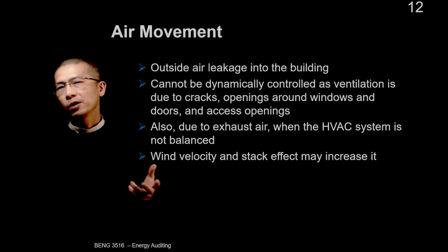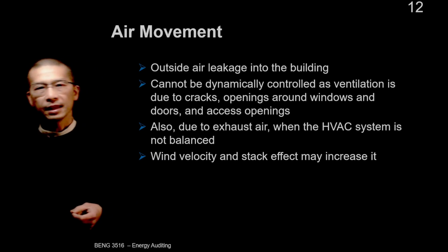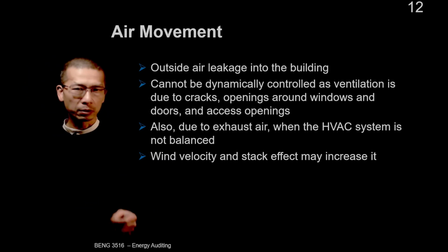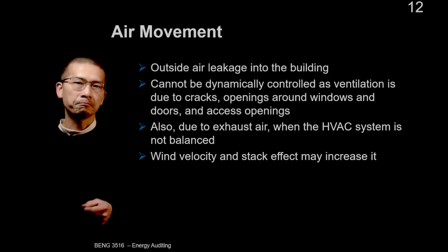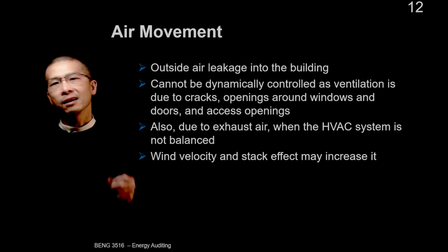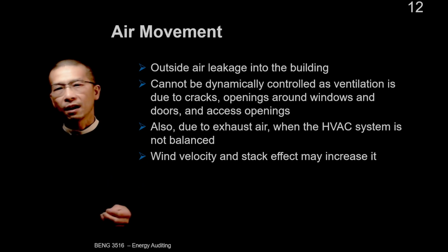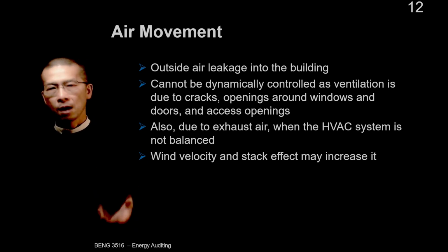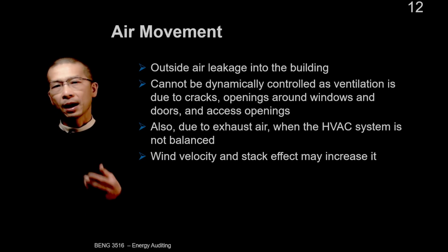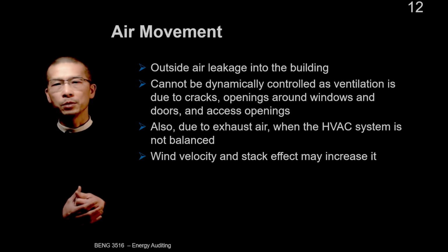While we often focus on installations, infiltration is frequently the silent killer of building efficiency. By definition, infiltration is the uncontrolled leakage of outdoor air into our conditioned space. The key word here is uncontrolled. Unlike mechanical ventilation, which we design and cycle to ensure occupant health, infiltration happens through cracks and gaps in the building envelope.